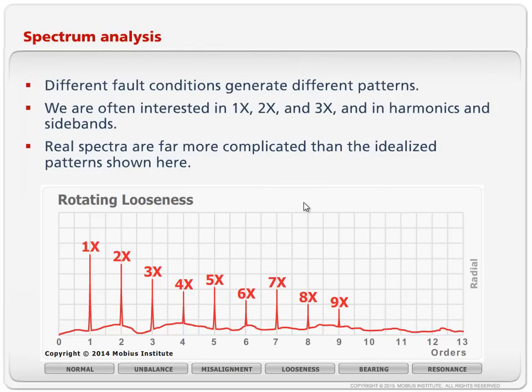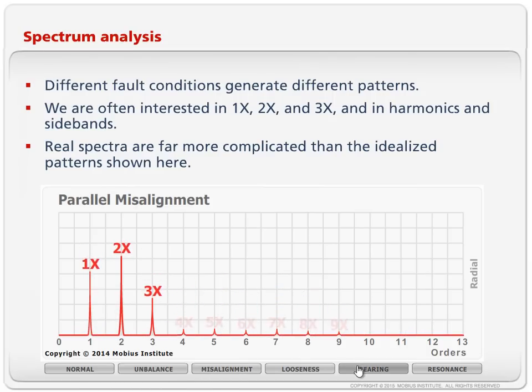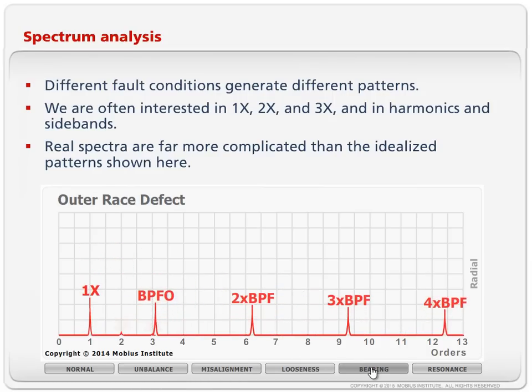And if you understand why the vibration changes the way it does, then not only do you make sure that you set up the analyzer to capture that vibration and you take measurements in locations that will capture it, when you see patterns like this or patterns like that or patterns like this for bearings, you won't just think of the wall chart, you'll think, aha, harmonics, what does that tell me?